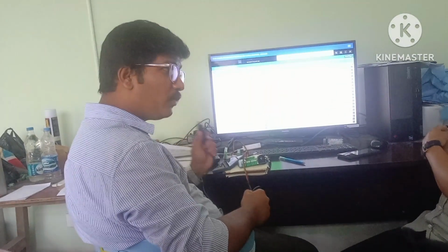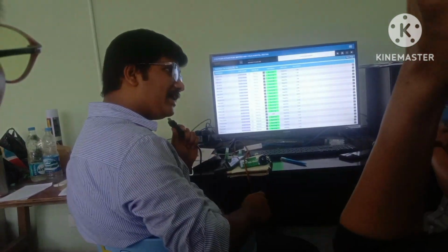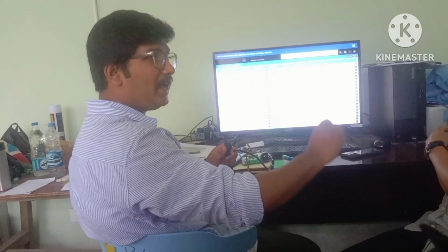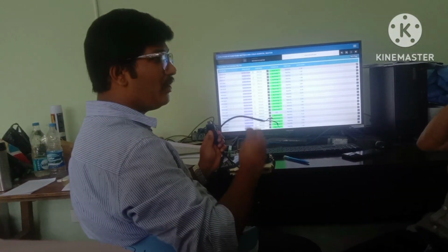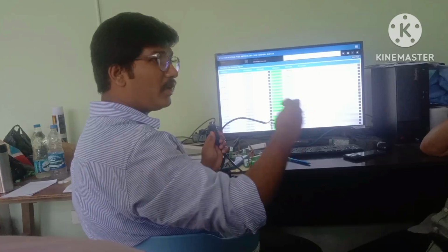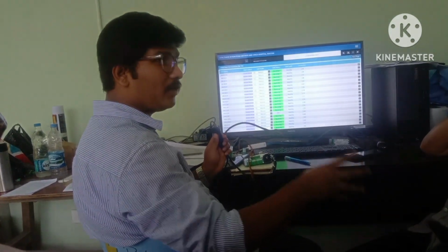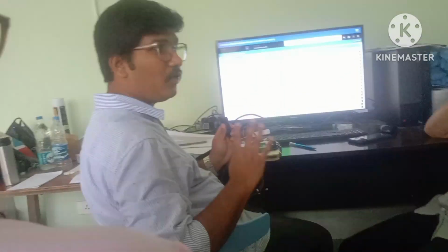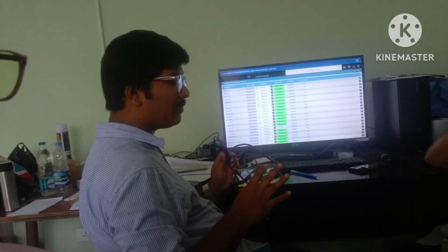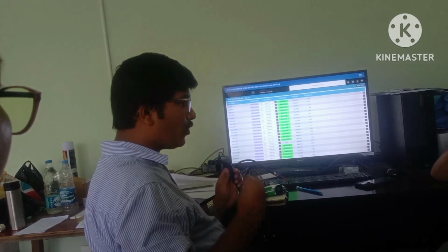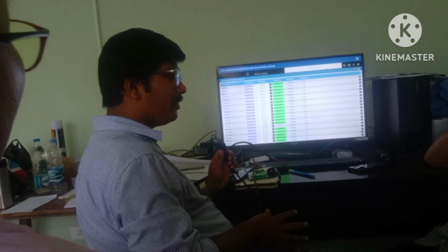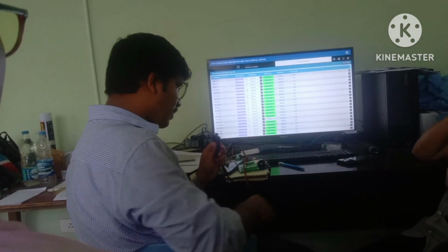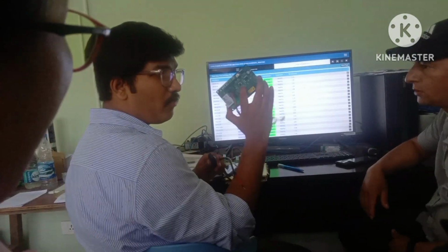In one device, I am getting everything at one point. I don't need to lay all the other cables: for command one cable, for feedback one cable, for analog command one cable, for analog input one cable. I don't have to lay separate cables, so my communication will not be slow, and there will be seamless connectivity in all the devices. For that we have used Modbus here.